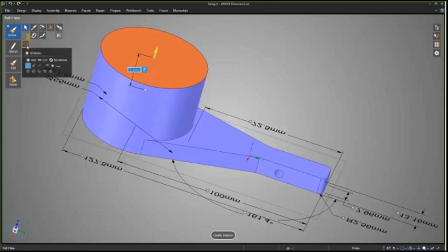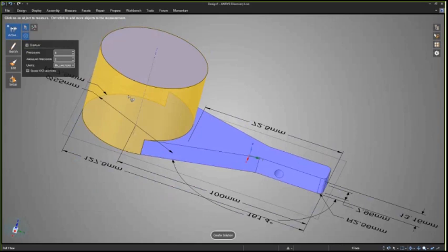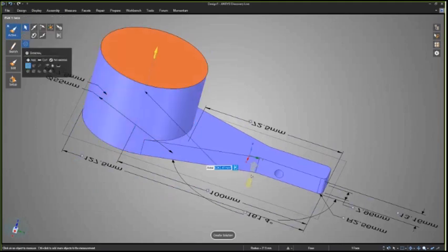And over on the left in Discovery Live, there's this options panel. And inside of this options panel is a measure tool. And so if I set up what I'm trying to pull, like this face here, and then I take a measurement like the surface area of this face, I can click on it and now drive it. If I type in 6,000, it'll drive it down to that value.